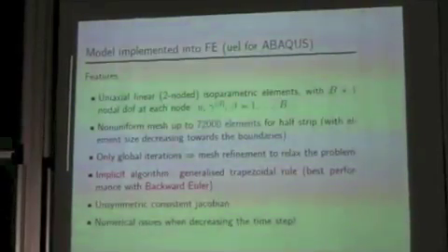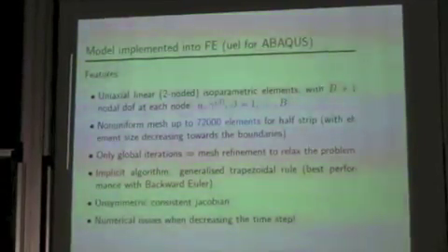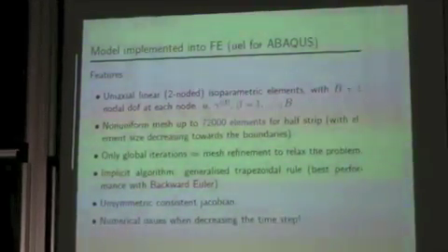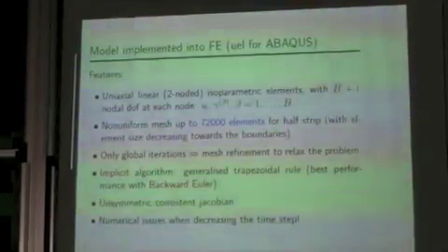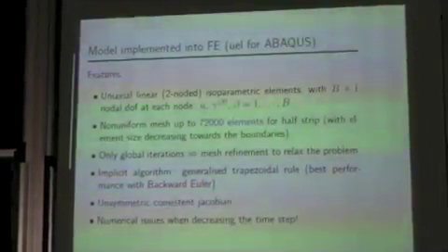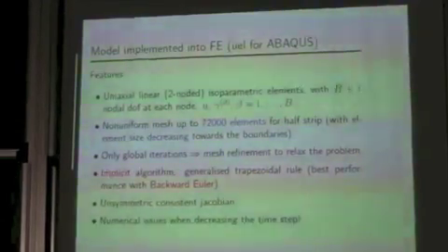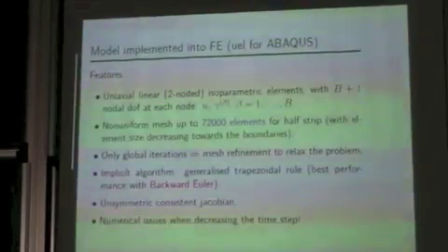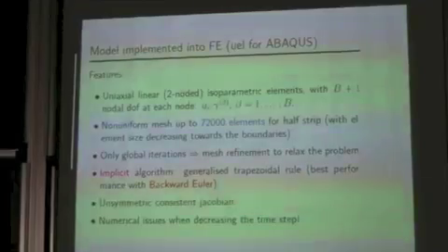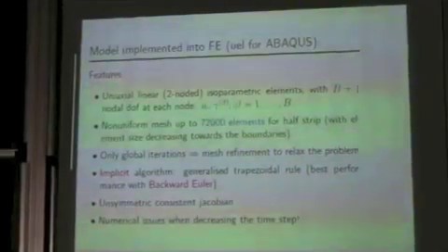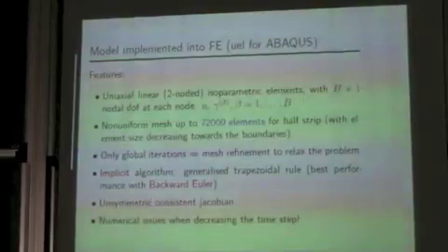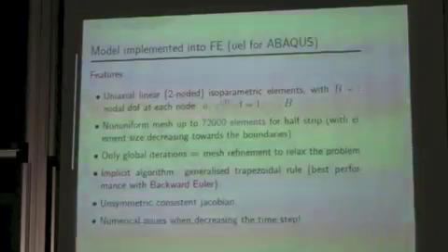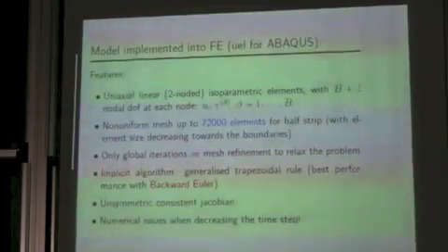So, since the problem is unidimensional, these are just linear elements. The convergence: my aim, since many friends of mine implement strain gradient plasticity, and they usually use general purpose elements, for instance for the plane case, and in order to have convergence, they usually use an explicit integration scheme. I wanted an implicit integration scheme, and I was hoping that for just a uniaxial case I could reach convergence. Actually I could, but it was very hard.